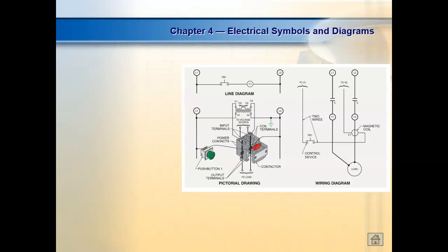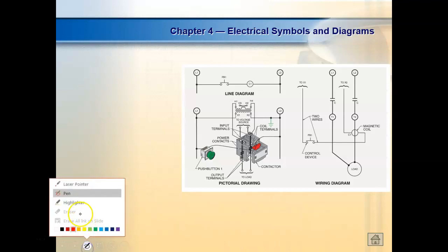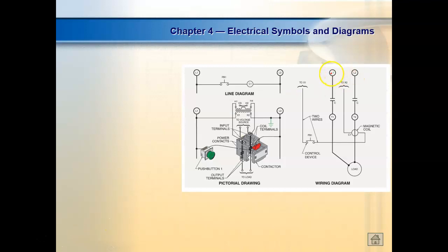So normally in controls, we have two circuits. We have the control circuit, and then we have the power circuit. This is usually drawn as a wiring diagram, which is very complicated because they draw the control circuit along with the power circuit. But this is the actual power circuit right here. So we come through, there's contacts. What's it being controlled by? It's being controlled by that relay right there. It has the same name, right?